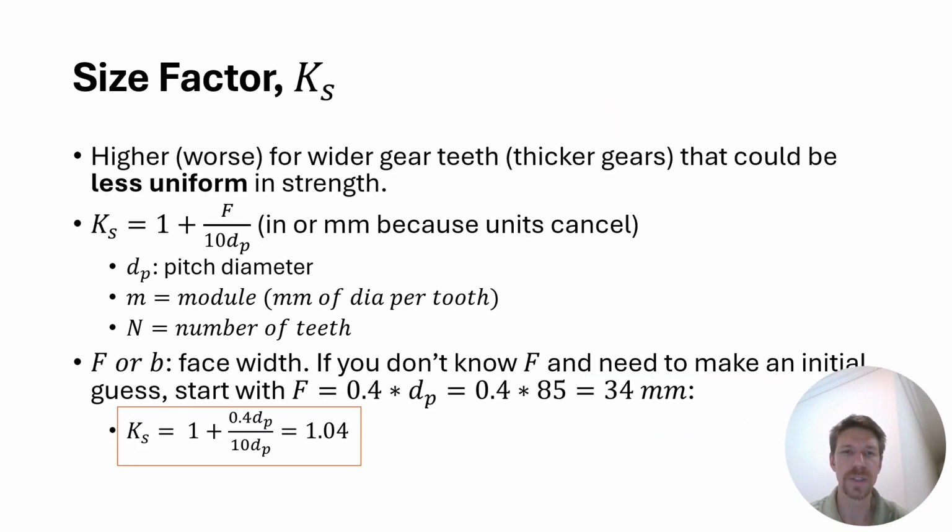The size factor, again, it's worse for wider gear teeth, and it depends on the face width, and that's what we're asked in the problem to determine. So we don't know the face width. So if you don't know the face width, you need to make an initial guess.